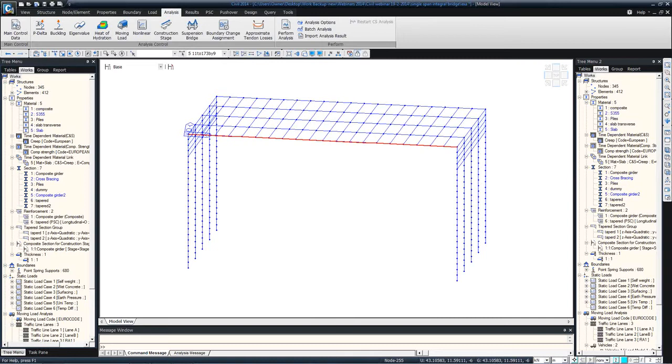There is another question. The vehicle load for the case of special vehicles where we have straddling. The lane width is say 3.6 meters and the wheel spacing is 2 meters. So actually for the straddling vehicles, what happens is if you specify 2 lanes between which the vehicle will straddle, the software internally creates multiple lanes between those 2 lanes and places the vehicle on different lanes with the 2 meter spacing, and then gives you the worst effect.